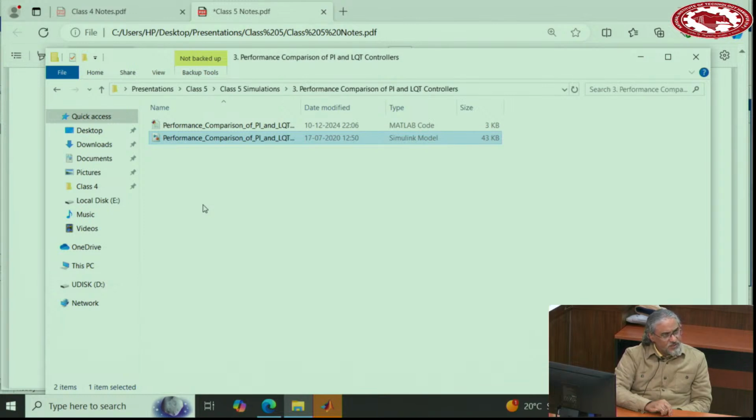No, because grid voltage, especially when we say AC grid voltage, but here in this case a DC grid, always if you have a grid, that voltage is distorted, right? And then when you measure, there will be sensor noise anyway, plus the distortions of the AC grid, harmonics and those things. But DC grids are not very common, so we cannot say too much about that.